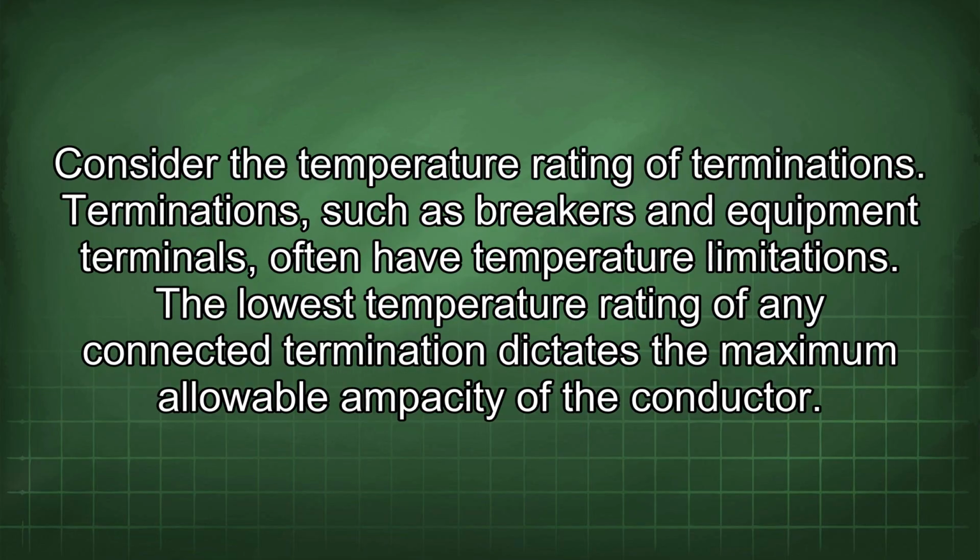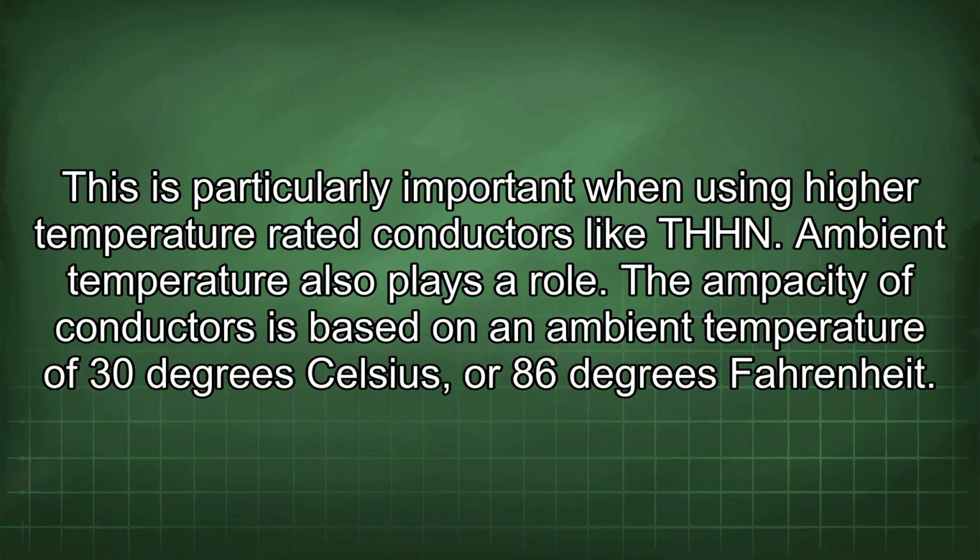Consider the temperature rating of terminations. Terminations such as breakers and equipment terminals often have temperature limitations. The lowest temperature rating of any connected termination dictates the maximum allowable ampacity of the conductor. This is particularly important when using higher temperature rated conductors like THHN.